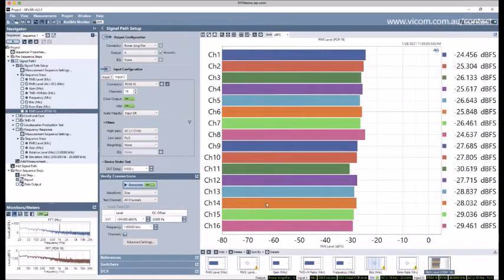And this is quite useful because since I have calibrated my source speaker at the reference position, so at the reference position I have a sound pressure of 94 dB SPL, I can actually read the sensitivity right here. I've got minus 24 dBFS, and I happen to know that the sound source is 1 Pascal. So this is minus 24 dBFS per Pascal.